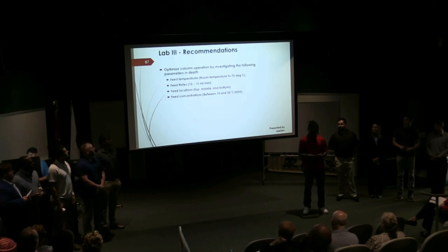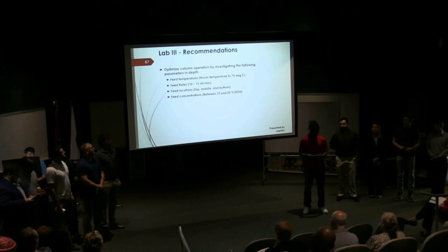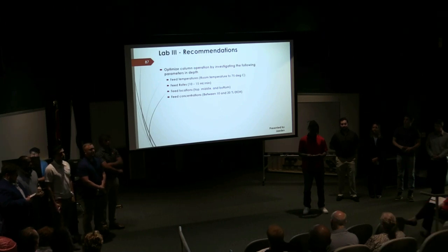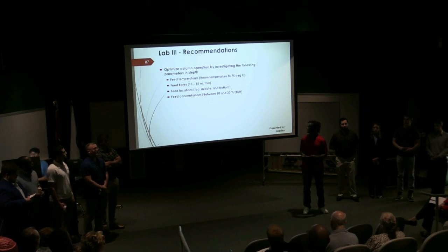And for recommendations, we think that for continuous distillation experiments, we can optimize the column operation by further investigating parameters like feed temperature, feed rates, feed locations, and our feed concentration.